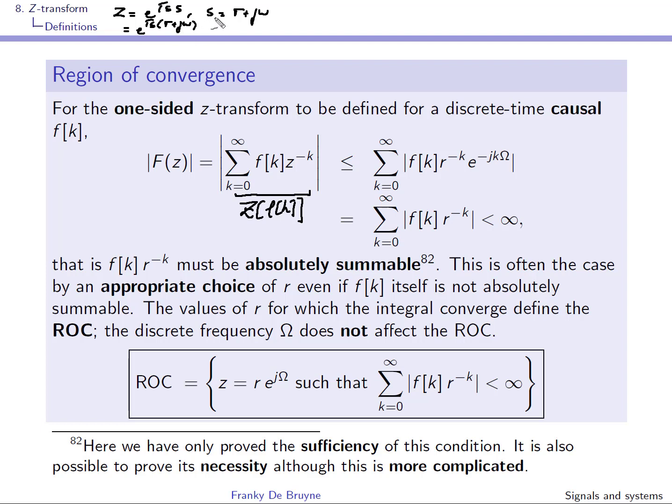It's just putting the expression of s in the expression of z, and this one you can rewrite as e to the Ts sigma times the exponential of j omega Ts. This is a real number and we'll call it r, and we'll define here a discrete frequency so that we can write z under the following form. So it's a polar form.